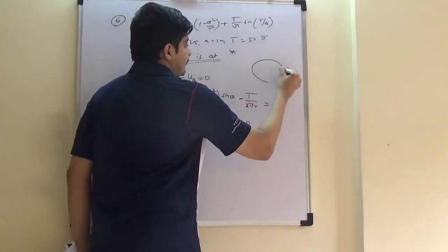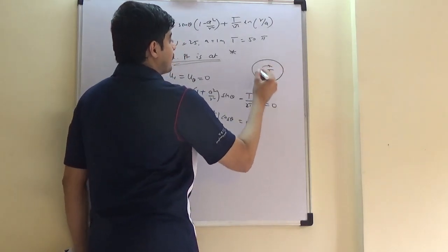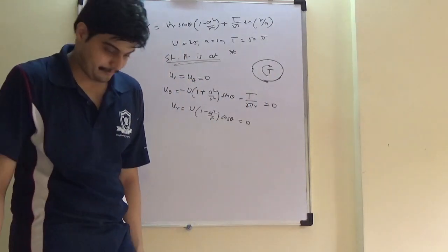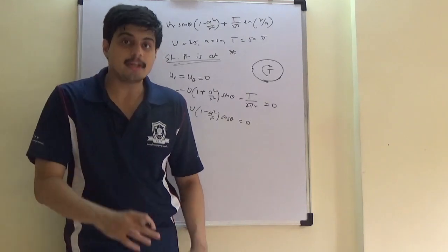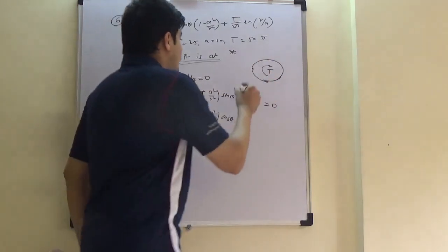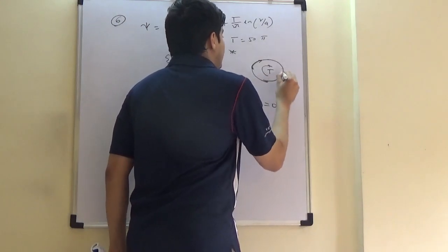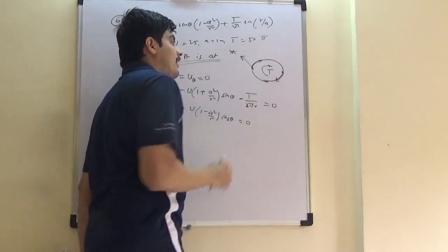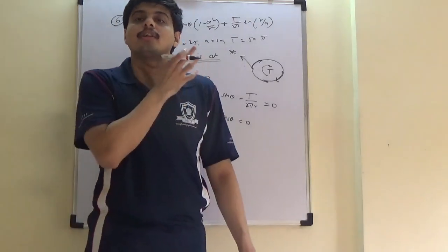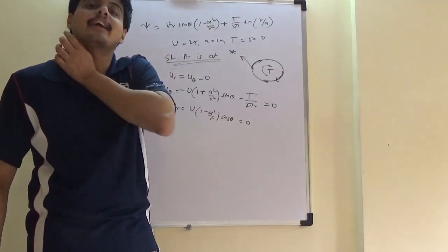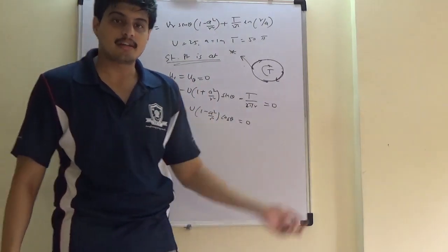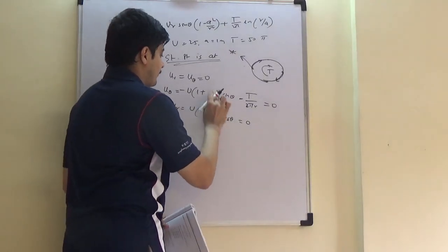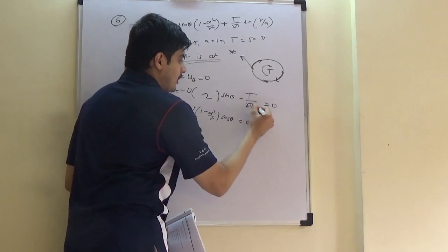Most important, just because you rotated the cylinder, would the stagnation point be on the surface or away from the surface? It has to be on the surface, because rotation just shifts the stagnation point on the surface because of circulation. It does not push it radially. It cannot. It is just a rotational motion. It is not source or sink motion which has radial direction. It is only tangential flow. Tangential flow can disperse things tangentially. So r is equal to A is known.